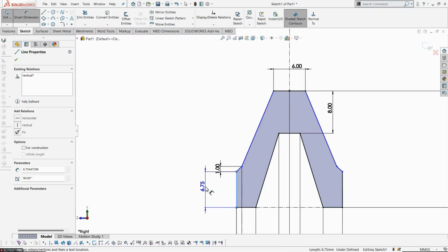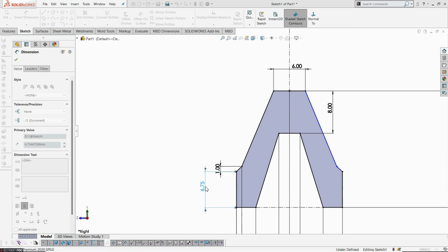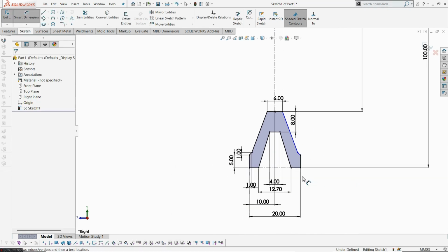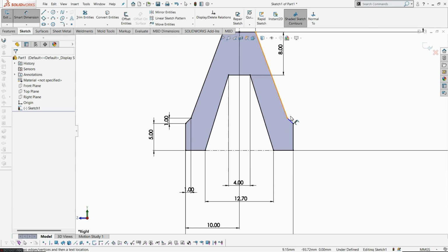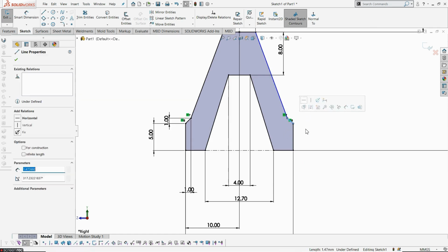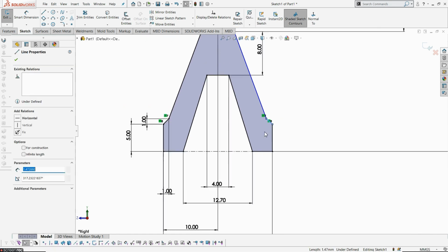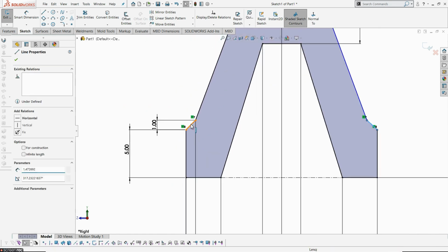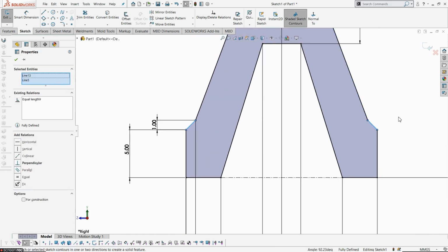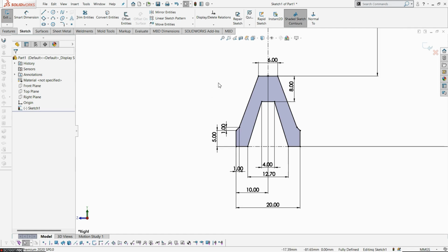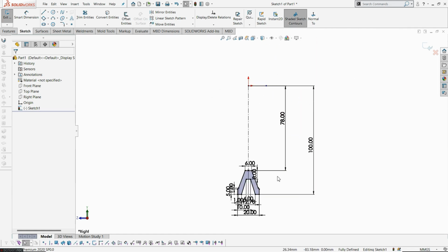Now I am arresting the profile with the recommended dimensions of 5 mm vertically. Once I arrest it, look at it, the other endpoint only needs to be arrested. So selecting this line as well as the constraint line, and use equal geometrical constraints to fix them in equal length. Okay, now the entire profile is drawn. Then using the revolved boss option to make a solid body.